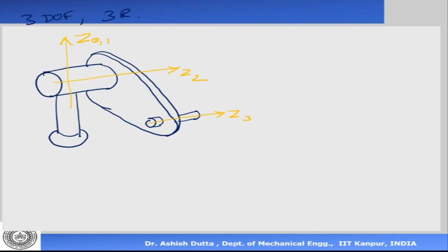Okay, so we have put our z-axis. Now we have to put our x-axis. Now for the x-axis, again note that Z1 and Z2 are intersecting axes. Okay, and hence there is a 90 degree angle there. So it will mean that your x-axis will be coming outside x2. Now since x2 is coming that side, we put X0 and x1 also along that. And here is my x3. Okay, so we have finished our x-axis.